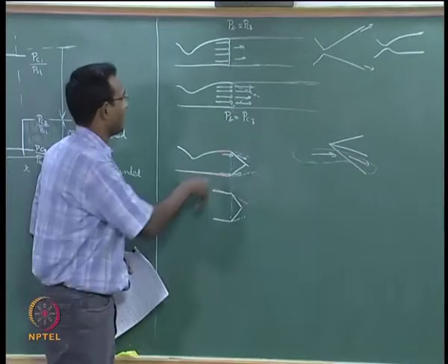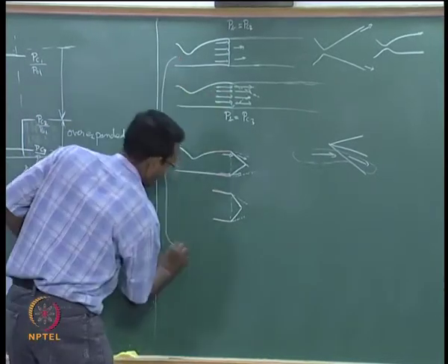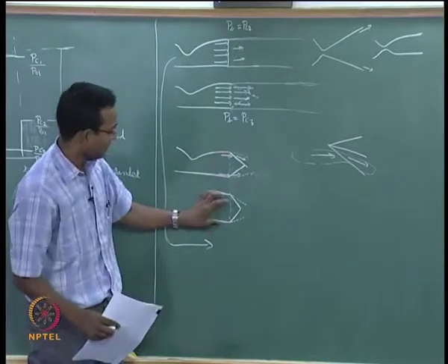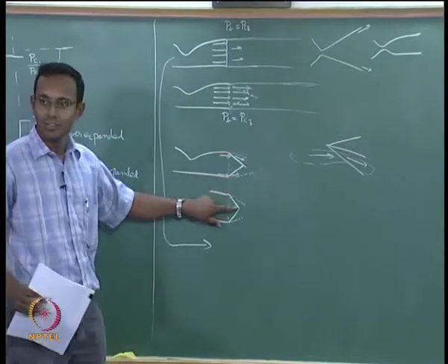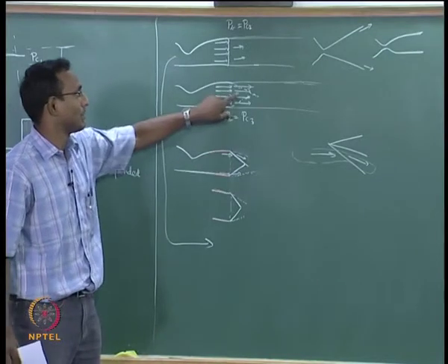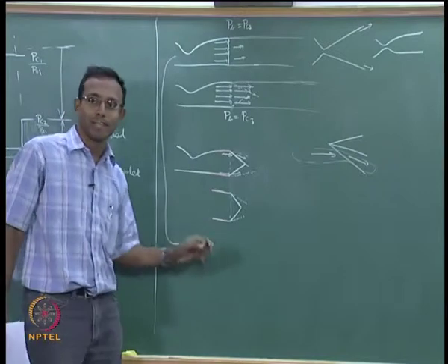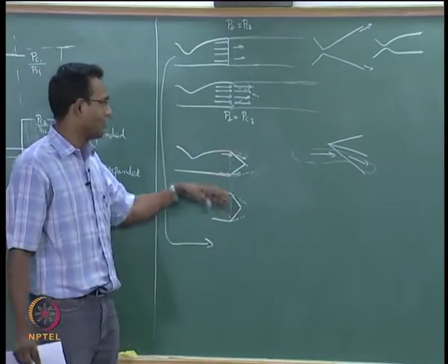Okay. Of course, I have not drawn it the correct way, this picture should have been in here. Okay. That is the full normal shock. It becomes a high angle oblique shock, to a lower angle oblique shock, to eventually becoming a Mach angle. This is the whole thing that is going to happen as I decrease my back pressure. It is going to tend to this finally.